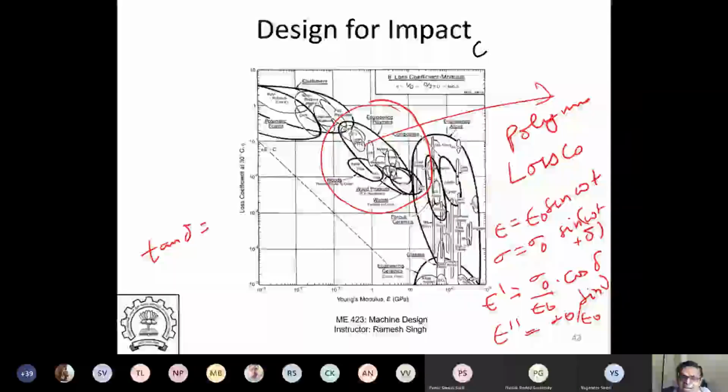Light and strong. That is true. Impact strength, right? What do you mean by impact strength? High fracture toughness, high tensile strength? I am designing a body armor. So toughness, these are all right answers. You need high fracture toughness. Primarily you need impact strength, is the right word, because it has to absorb a lot of energy and it has to be lightweight, right? So what is the material of choice?